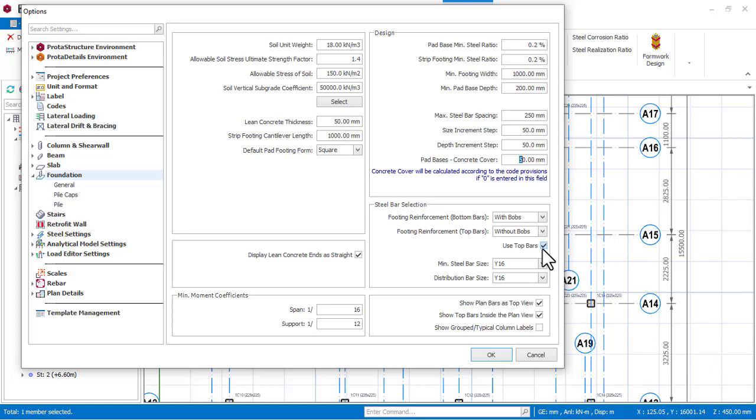Okay, but right now I'll have to remove my top bars, except along the line we have to see a combined footing or a footing that is very wide, like let me say 2.5 or 3 meter by 3 meter, which is not really adequate to use that. Then you cannot choose to use a top bar for that. But for now, I say no.